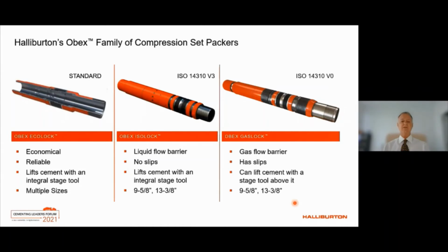Additionally, the OBEX compression set annular packers will support second stage cement, reduce hydrostatic pressure on the formation, achieve cement to surface, stop annular flow during primary cementing, eliminating sustained casing pressure. There are three types of OBEX packer available for providing an additional mechanical annular barrier.